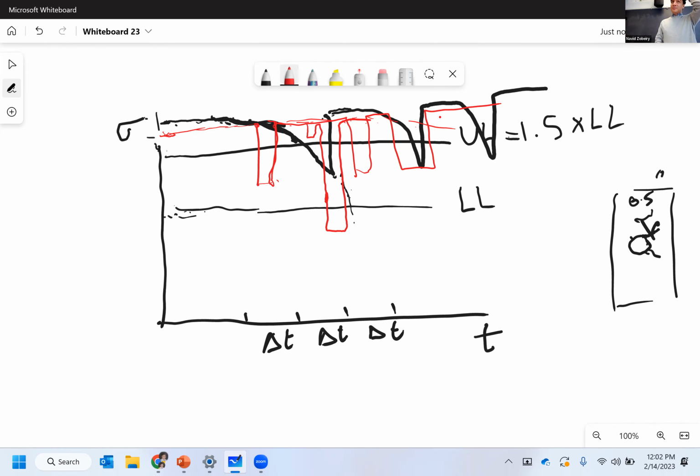So the idea that we have, the mentality behind certification, is to understand the nature of impacts, estimate the effects and the strength, come up with a strategy to repair them. And so this is another thing which is on top of what happens to metals. If there is an impact, show that in the lifetime of the structure, there is no crack growing around the impact. That's an extremely severe punishment for composite.